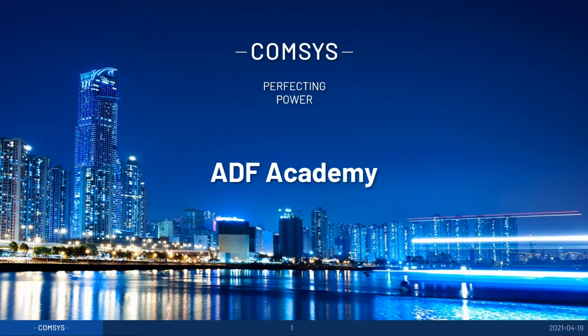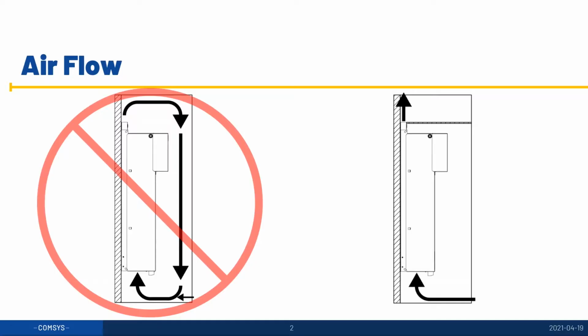To succeed with a commissioning, the most important thing is of course the installation of the active filter. And the bigger factor here is the airflow. We need to make sure that nothing is limiting the airflow of the active filter and nothing is preventing the air from flowing in the correct way.